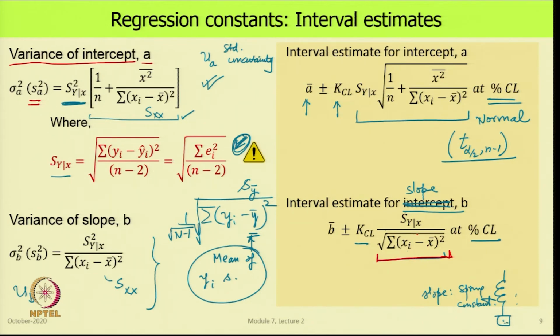What one does is minimize this whole thing as much as possible. How can I minimize the sum of (xi minus x bar) squared? Take lots of data points. That is fine. So, if this is the range over which you are doing calibration, you could take equally spaced, say 5 points, 7 points, 9 points. Somebody else comes and says, no, let us improve the uncertainty, make it narrower, let us take twice as many points. This denominator term will increase further.